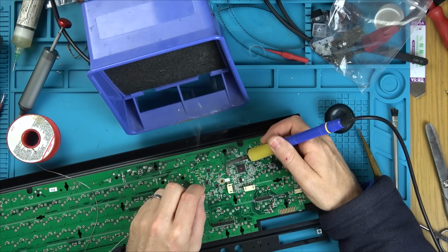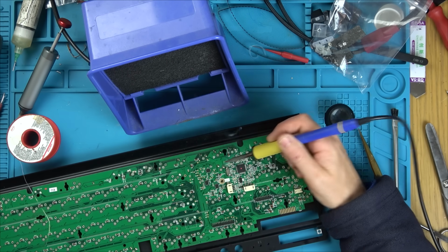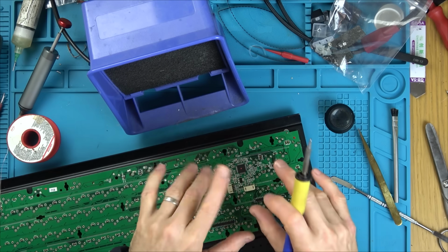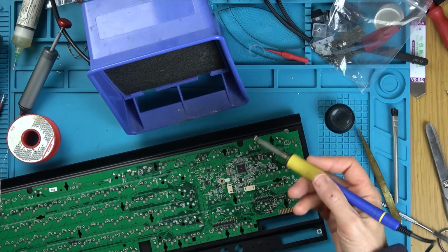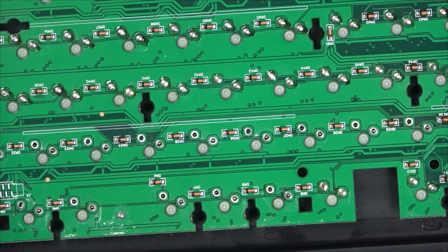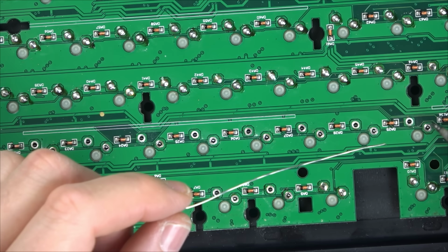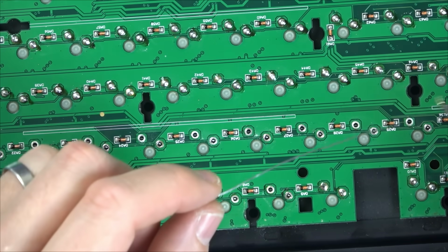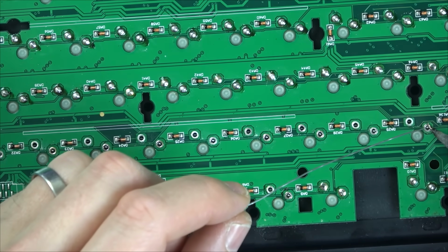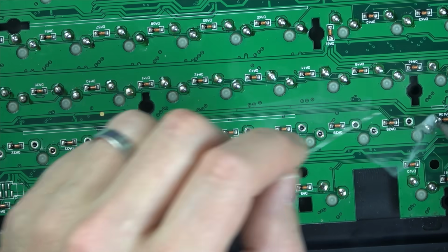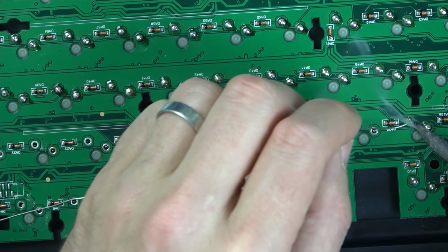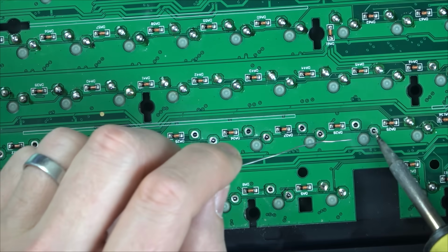And I'm adding plenty of solder in there to make sure it goes right down into it, because with all the whacking it might be easy to get a cold solder joint. It is actually incredibly quick once you get going, and I've been lucky. I've only had to undo about 5 keys so far. So watch this, I'm going to do this little row here. It's nice because if the solder's straight you can just feed it right in. So clean the tip, check this out. Heat it up and just watch. Feed off, feed off. So it's just really, really quick.